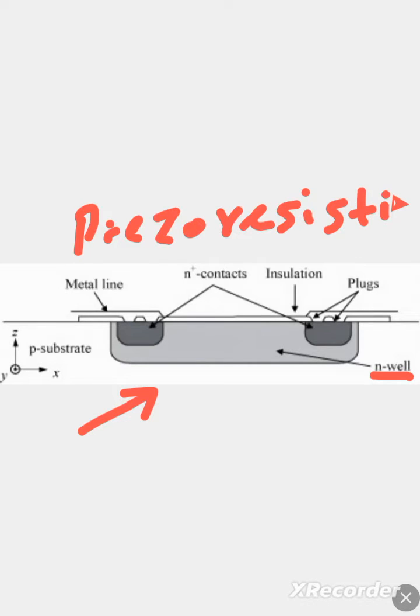So you just have this resistor like this, with two ends, and this is a p-type substrate where the x-axis or x-plane is as shown, and this is your z, the z plane is in this direction as shown by the arrow, and y is the out of plane. It means out of this screen and back into the screen. So this is how your piezoresistors are fabricated using semiconductors.